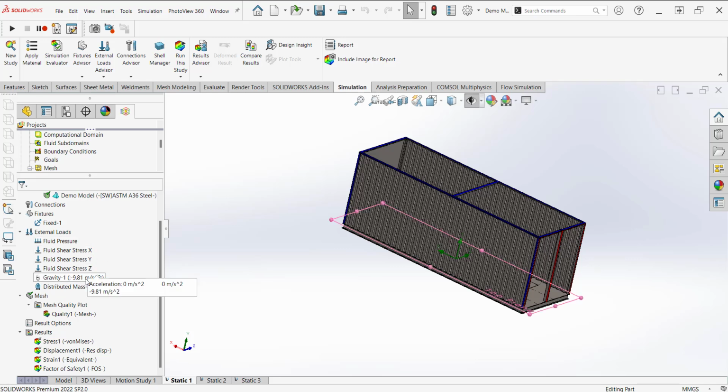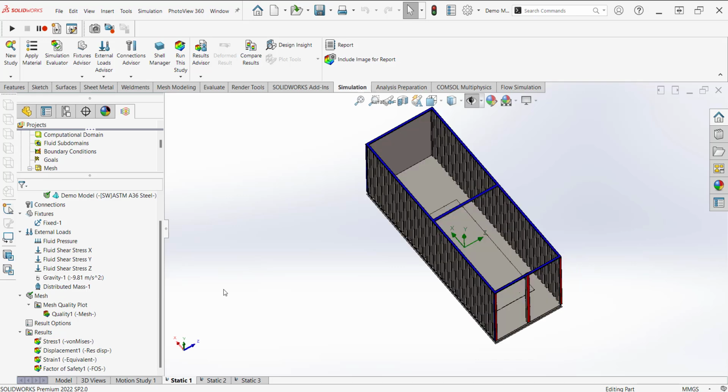More than that, we need to define the gravity load, and when defining this load, the program takes into consideration the self-weight of the structure itself. More than that, we have a value of distributed mass of 13,200 kgs, and this represents the mass of the generator itself.